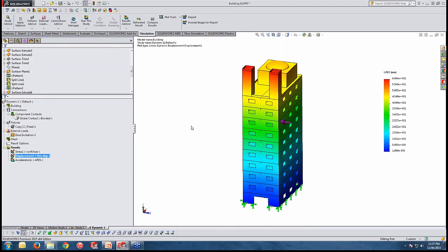All right, so what is very important to understand, we are getting mostly positive values when we do the response spectrum analysis, and as we said, this is a statistical method of combining the peak response of the structure in different frequencies when we enter the graph spectra. That is again a very good estimation when we have huge models such as a building. Well, it might take a very long time to resolve with the nonlinear dynamic.